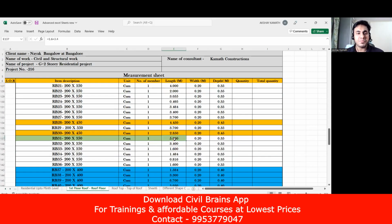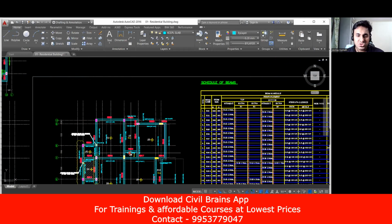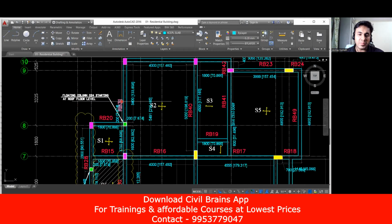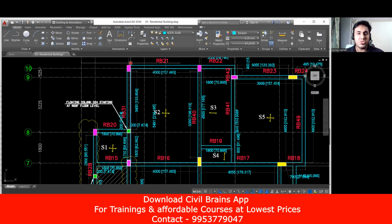Once this is done, next there are a few things you need to understand. See, one thing is RB31. I'll take you to the AutoCAD drawing of RB31. RB31 should be somewhere here. Yes, RB30, and this is RB31. This entire thing is RB31, from here to here. So in AutoCAD, you'll take the complete length from this column inner to this column inner.